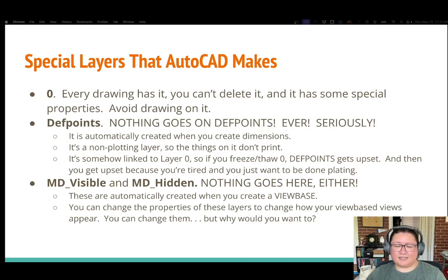Can you? Yes, for most of the time it doesn't have any negative impact, but it can if you aren't careful. So it's there. Try to ignore it. Go ahead and make yourself another layer to work on so that you aren't drawing on layer 0. The second layer that AutoCAD makes that you need to be careful of is the Defpoints layer.